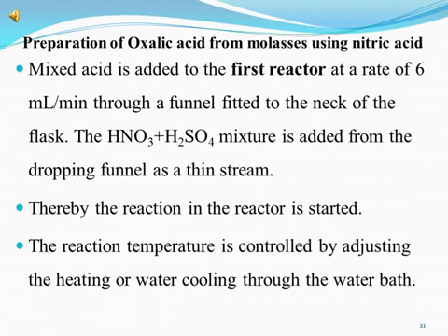The nitric acid and sulfuric acid mixture is added from the dropping funnel as a thin stream. Now, thereby the reaction in the reactor is started. The reaction temperature is controlled by adjusting the heating or water cooling through the water bath.